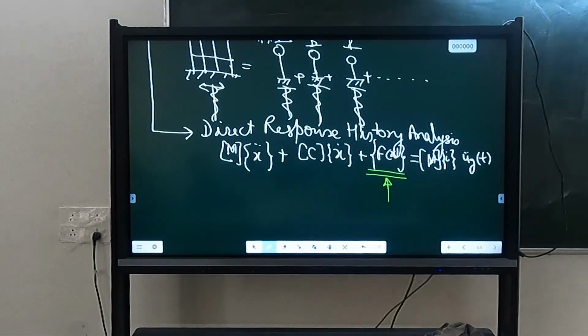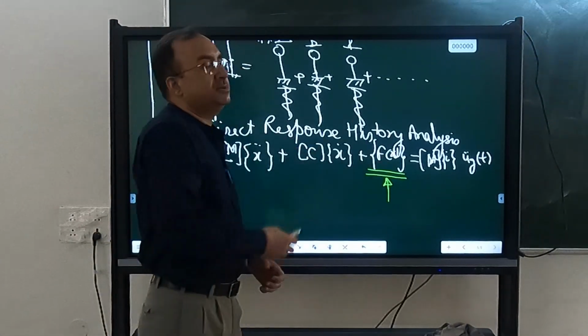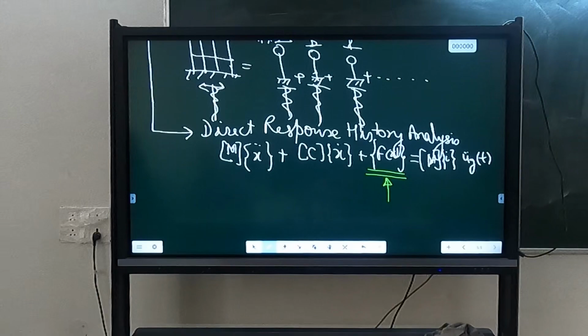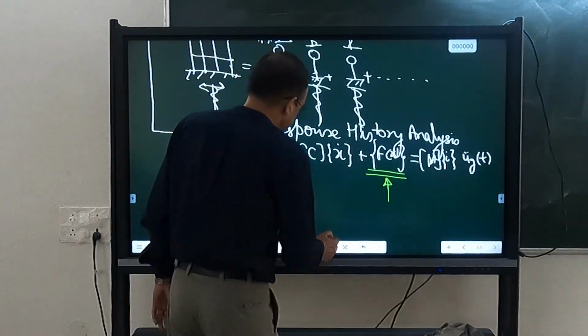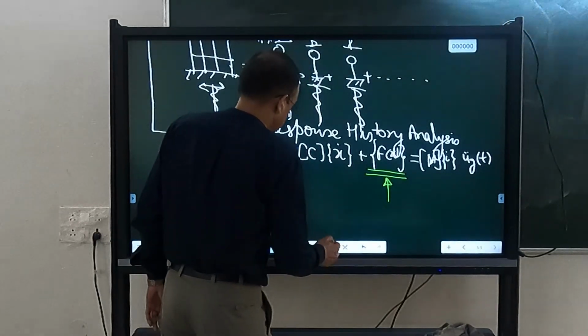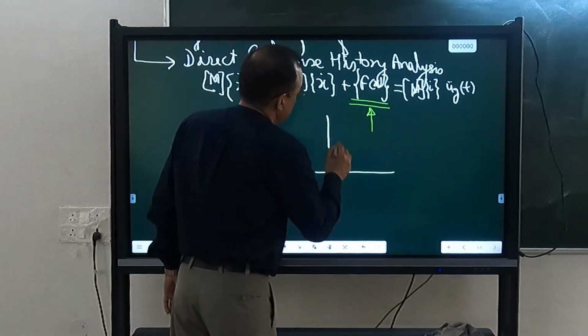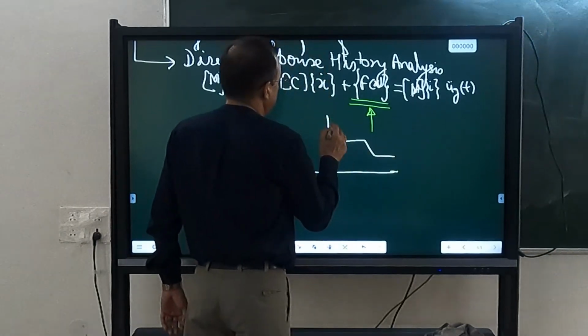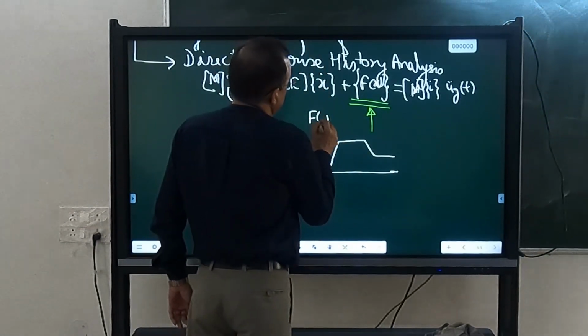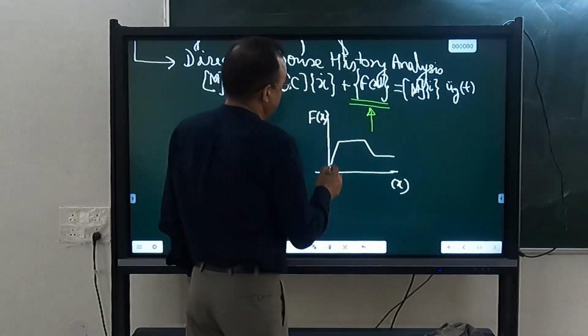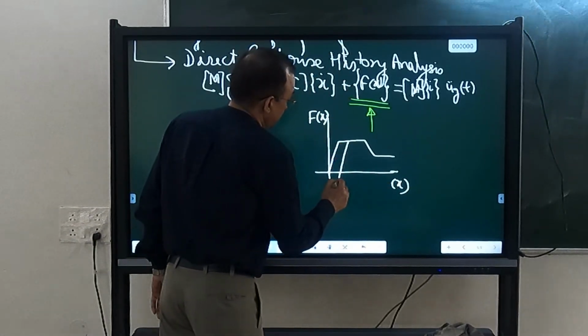If we have to do it analytically, then Fx also comes from certain predefined rules, that is, how the load versus displacement curve will change with displacement, and that too under reversible displacement. So you have to input what we call the backbone curve, which we have discussed, and also the hysteretic model.